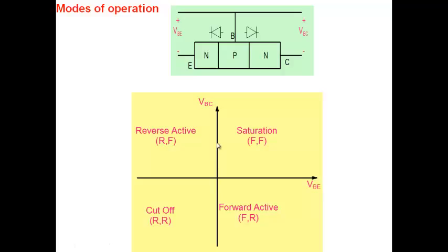Okay, the transistor may, if you're not careful, go into saturation mode. And we'll see pretty soon that once the transistor is in saturation mode, it cannot amplify. Amplification is only possible in forward active mode. In saturation, the transistor cannot amplify. So if you're biasing it in forward active, because of circuit variations or other means, if it does slip into saturation, the amplification will stop.